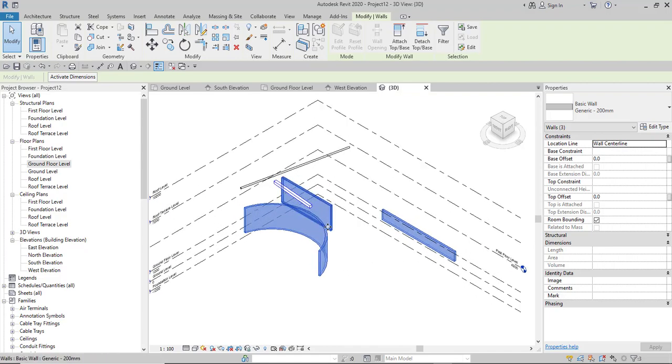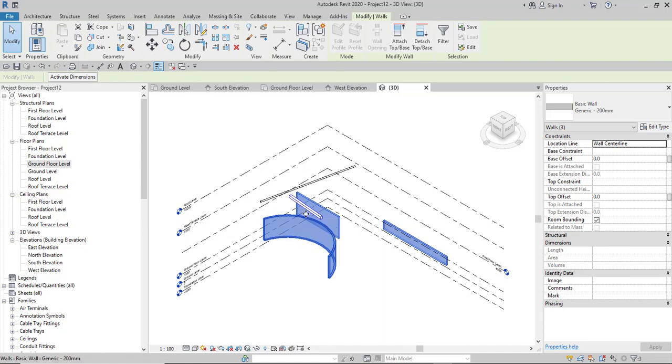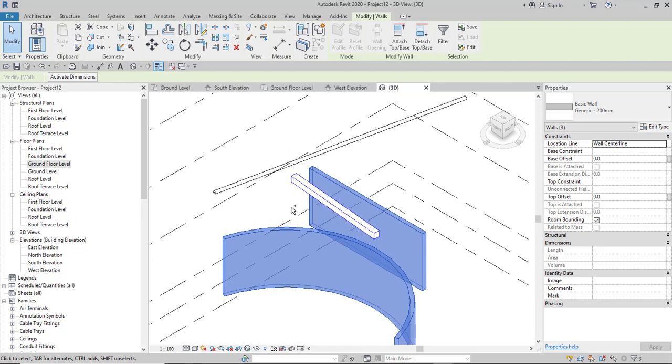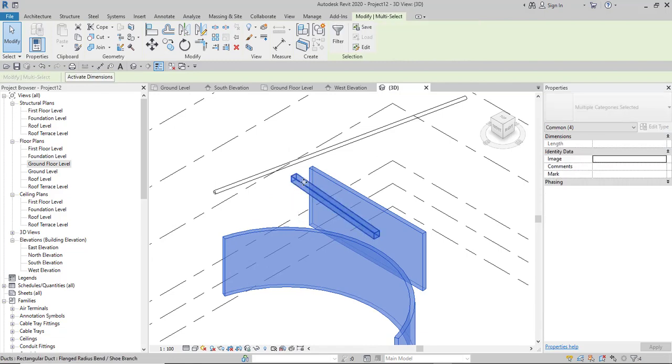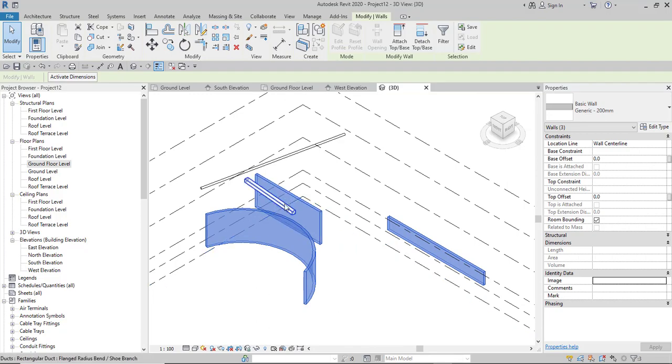But if I've selected 3 items, then I want to add another selection, or I want to deselect an object from the list, what do I do? That is where the keyboard comes in, and you have to learn how to use some of these things. If you use Control and Shift, if you press Shift, you see a minus. Then if you press Control, you see a plus sign. So what it means is that when you press Control, you can add to the list. But when you press Shift, then you can subtract from the list. So you use Shift to deselect an object. You use Control to add an object to an already existing selection.